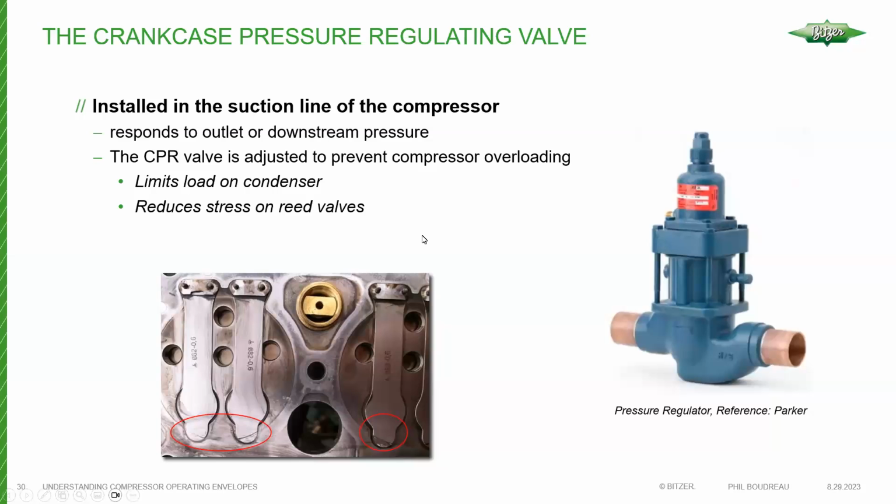This is something I learned many years ago when I came on board with Bitzer, that discharge superheat is very important. It just makes sense, because the overall superheat in the discharge is going to be a function of a few things: compression ratio, the type of refrigerant you're using, and your return gas superheat. And as it turns out, the discharge superheat is what we use to determine if we have enough separation of the refrigerant from the oil to ensure sufficient lubrication of the compressor.